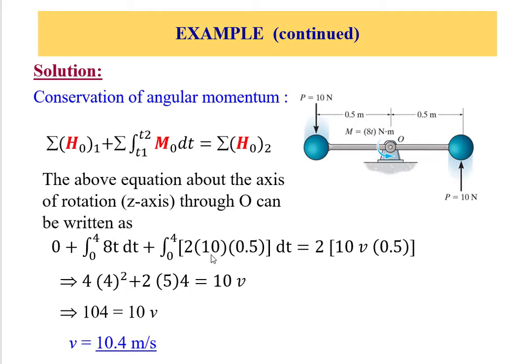So we have 2 times 0.5 by 10. Or if you don't like that, you can say this is a couple because the forces are equal. So the moment produced by these two is 10 multiplied by the distance orthogonal to the vectors P, so it's 10. I advise you to look back to statics and look into the definition and how to compute moments.